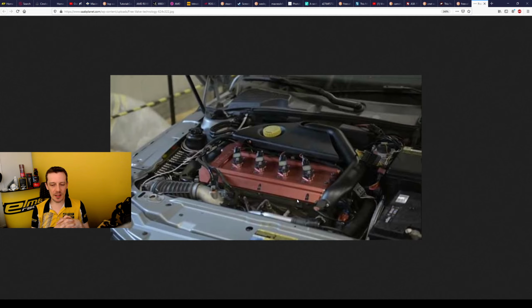it depends a lot. In relation to running super stiff valve springs, it could probably be doable to run this with a similar energy loss. But if you had some kind of variable valve spring system, like a pneumatic valve spring system or something like that, then in that case, I don't think you can have a free valve system get anywhere near the energy efficiency of having a mechanical opening and a pneumatic valve spring, because you can vary that by engine RPM and load to minimize friction losses. So I think you're always going to have way more losses running this type of system.